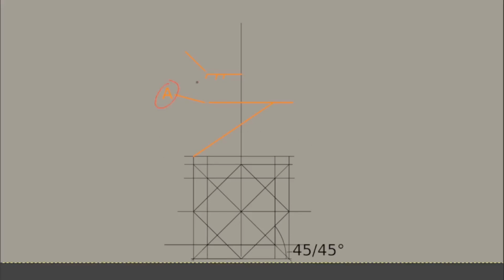Number 2. The bottom plane projection. First, a line parallel to the horizon A will be drawn to set the lens. This rear line will form the box that holds the rotated square. Then, using the diagonal lines, the smaller square can be found where the diagonals intersect with the converging lines. This will be the corners of the unrotated square, sitting on the bottom projected plane of the rotated cube in perspective, the Y-plane.